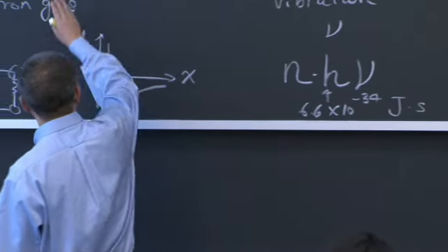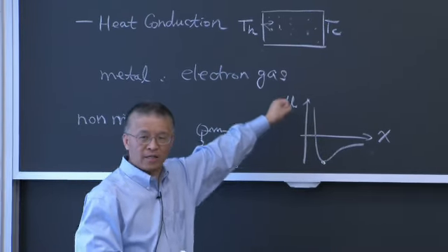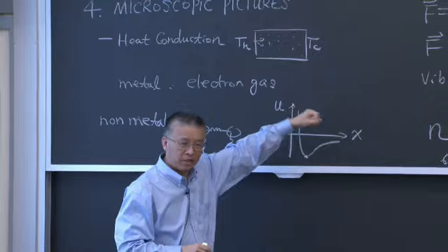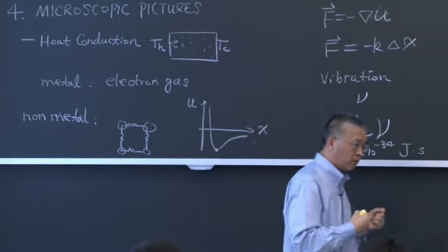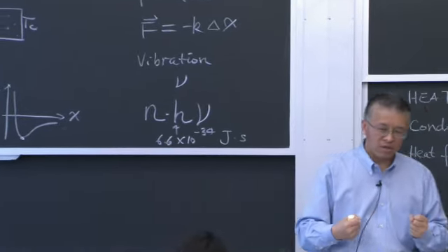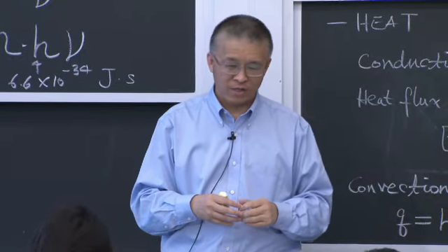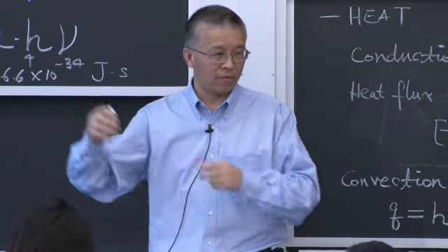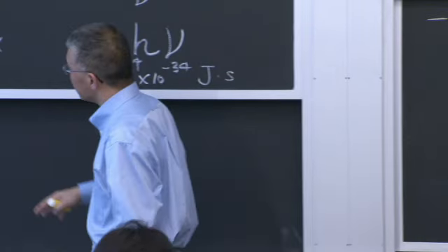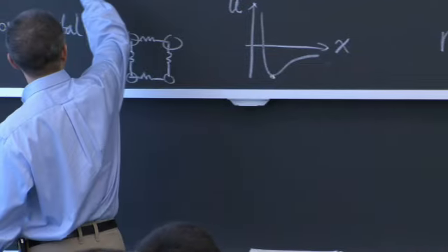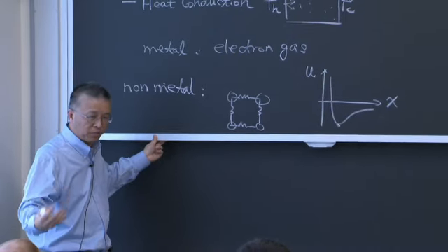When one side is hot, the phonons at the wall gain higher energy and go to the next. The phonon mean free path, from collisions between the phonons, turns out to be a wide range. We're doing quantum calculations on this, and some are 1 nanometer, others 1 micron. So for heat conduction, the basic picture is this gas picture.